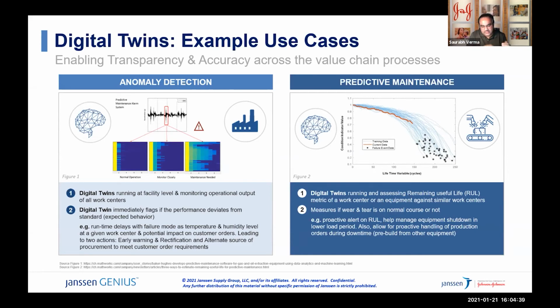Now, we created this golden batch as a reference, as a benchmark, and we started comparing it with the new batches. In one scenario, I know that we started to see a blip in the feed rate of a feeder of a particular raw material. It was, I think, media. And we were able to immediately stop that batch.